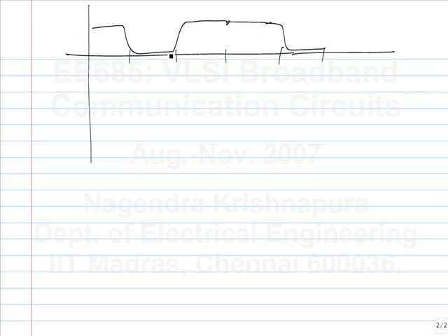So first of all, I think it looks like if you sample it only once in every symbol period, it's not very easy to tell. Okay, you will simply get the data and nothing else. Okay, so if you sample twice per symbol period, so I mean this is again contrived. I'm sort of leading you to the answer, but at least you can think about it. So when I say twice per symbol period, that means that you sample on the rising edge as well as the falling edge.